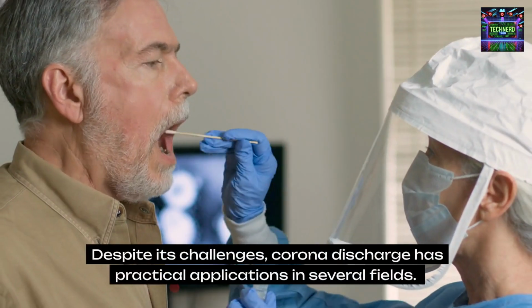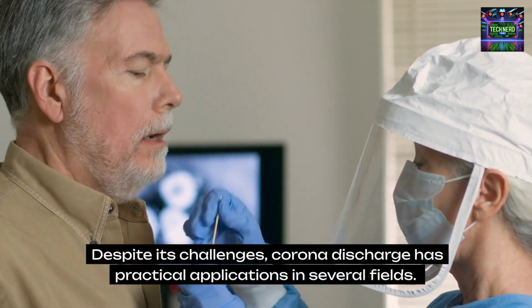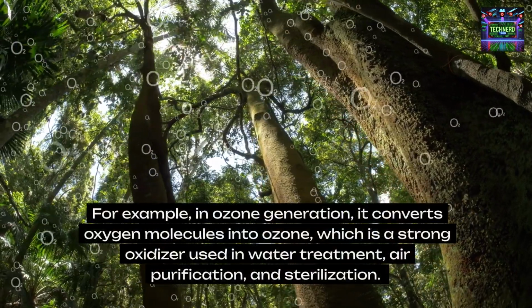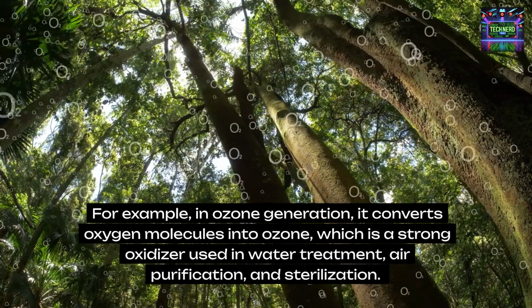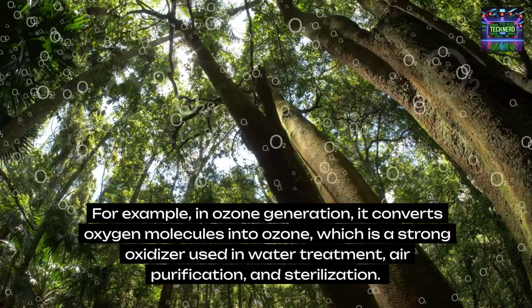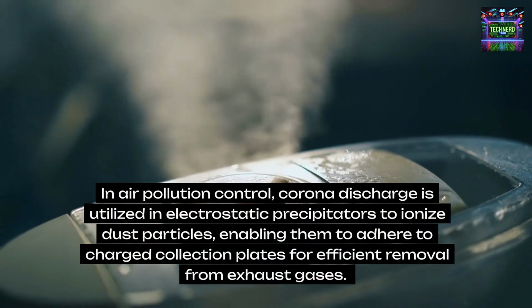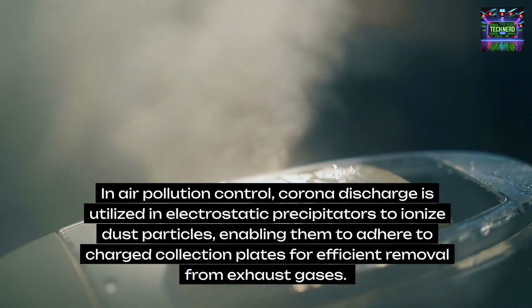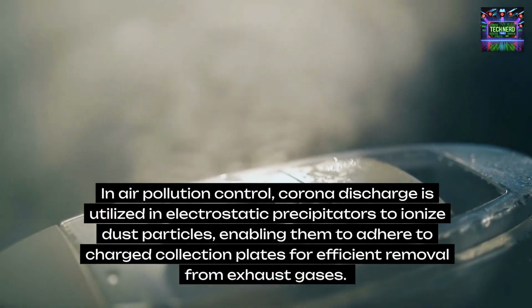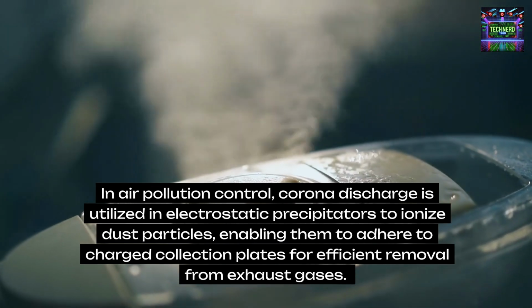Despite its challenges, corona discharge has practical applications in several fields. For example, in ozone generation, it converts oxygen molecules into ozone, which is a strong oxidizer used in water treatment, air purification, and sterilization. In air pollution control, corona discharge is utilized in electrostatic precipitators to ionize dust particles, enabling them to adhere to charged collection plates for efficient removal from exhaust gases.